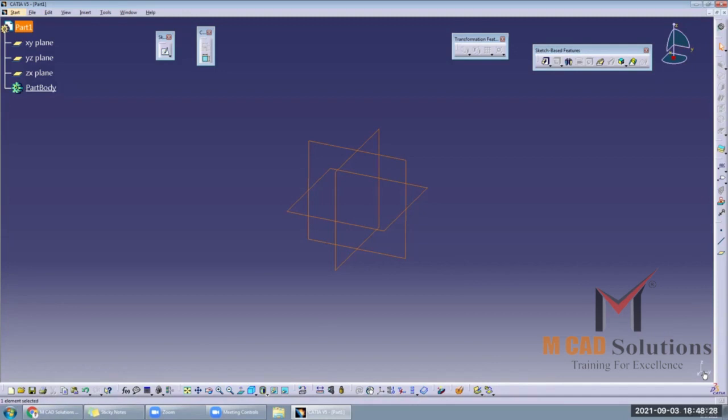For example, we are creating one assembly and we want to use that part for CAE. So we will save it and use it in the CAE software. That software will import the part. While importing, it should be placed at a particular location at the assembly level. So the CAE person will import that part and match our UCS, Universal Coordinate System, with the CAE software's coordinate system. So both coordinate systems are matched, and our part will be located at a particular location. That's why UCS is very important while working in different software.